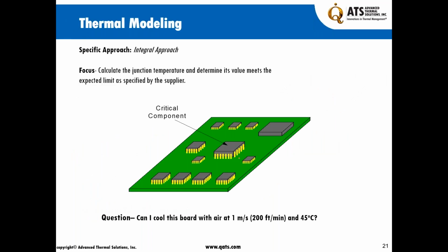Well, ironically, what a component sees on the board, which our objective in electronics cooling is to make sure what the junction temperature is for the worst possible ambient. And ambient typically is 55, or in some cases 70 degrees, in some cases 25 degrees, 35 degrees, depending upon the given workspace that you work with, the consumer electronics, biomedical, what have you.